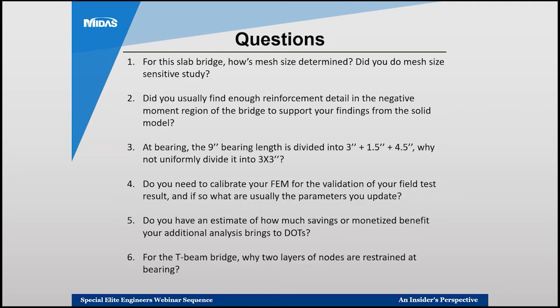Sure. So question number 1 says, for this slab bridge, how is mesh size determined? Did you do a mesh size sensitivity study? Okay, that's a good question. Yes, definitely the mesh size plays a role, and we have done this meshing and modeling for so many bridges, so we know roughly what the mesh size should be. In general, there are some rules that you would like to maintain for your mesh size. For example, you don't like to have an aspect ratio of more than 4. Ideally, we always prefer to keep our element aspect ratio at 1:1.